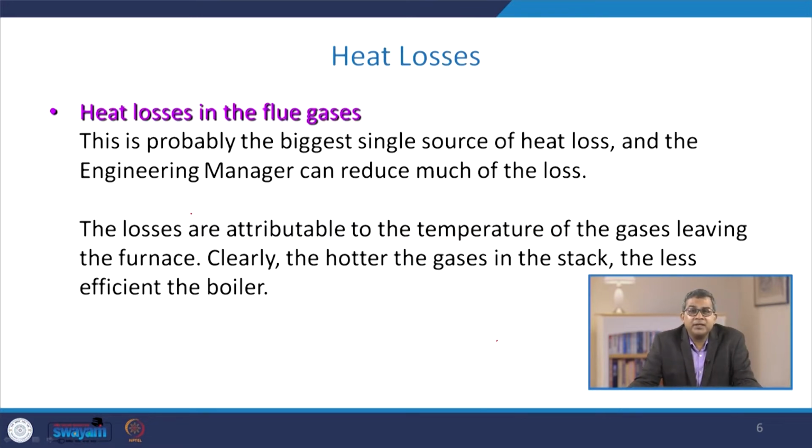Now, let us have a look at the heat losses. There are various heat losses attributed to the flue gas. And you can say the flue gases are the biggest single source of heat loss, and engineering managers or chemical engineers or any other engineers can reduce much of these heat losses by simply adopting various design measures. Now, these losses are attributed to the temperature of the gases leaving the furnace. Clearly, the hotter the gas in the stack, the less efficient the boiler, but you have to maintain a certain temperature of this hot gas to maintain the draft of those flue gases.